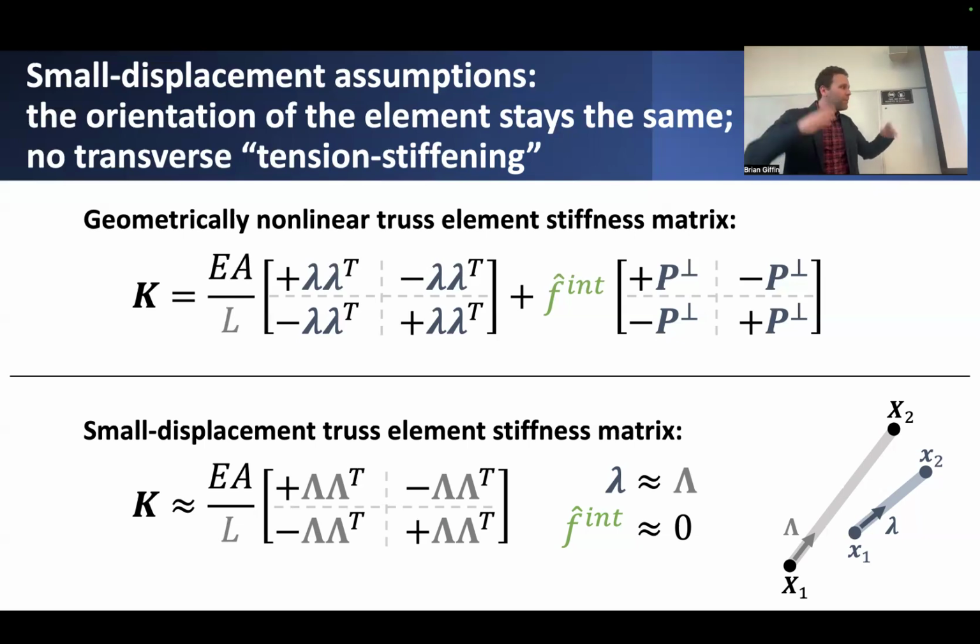So it all boils down to this: we could basically go with this expression, make a few modifications or tweaks to simplify it, making a couple of assumptions. And what we get back is the original stiffness matrix that we had previously derived under the assumption of small displacements or small strains. Kind of miraculous, although it shouldn't be too surprising that we should get this expression back.